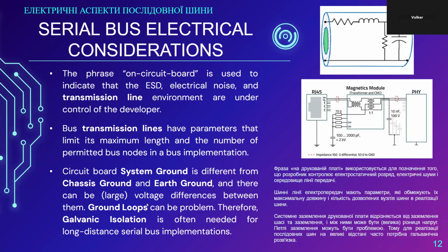What happens is that in the area between those two cables, magnetic fields will occur. It could be magnetic fields from motors, from lighting, all kinds of different magnetic fields are pretty much everywhere where there's electricity. These magnetic fields will induce a current into this loop. So now you have a current circulating between the grounds. And what that does is it creates a voltage drop.